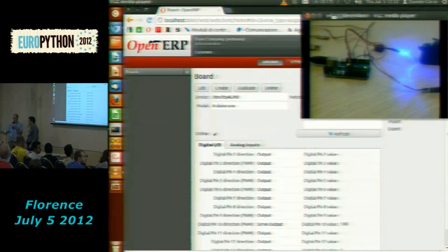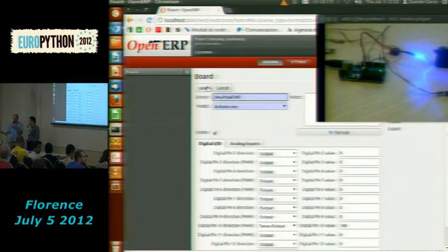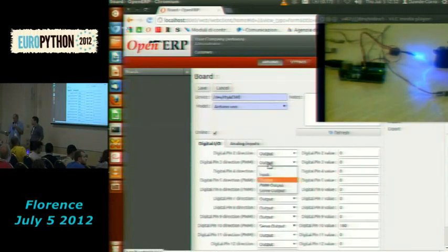Okay. It worked with the save. And the last thing to do is connect the buzzer to pin 3. Okay, let's try this. Output is okay. We can also try PWM later.